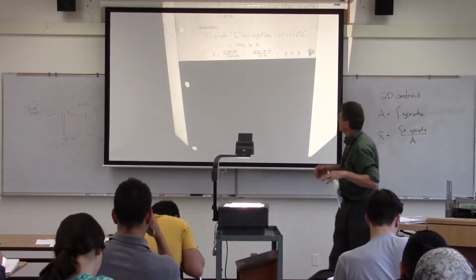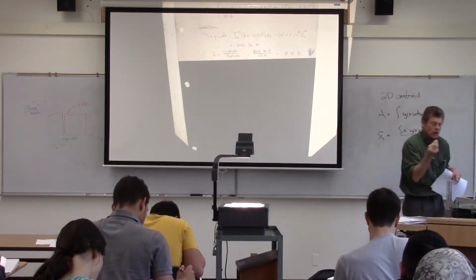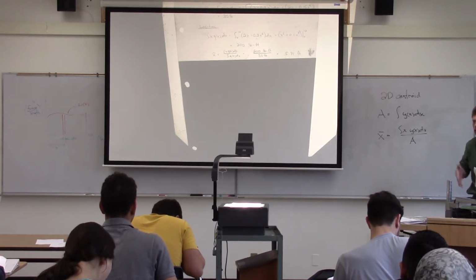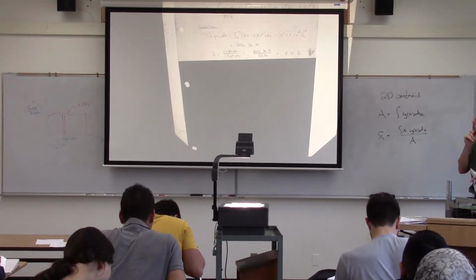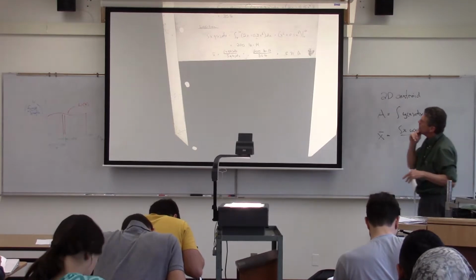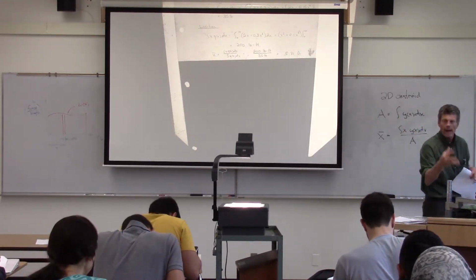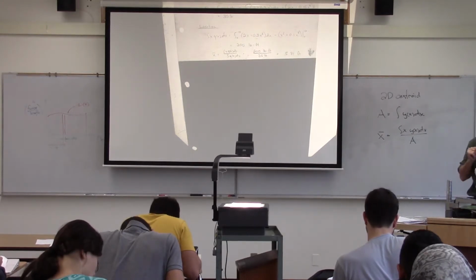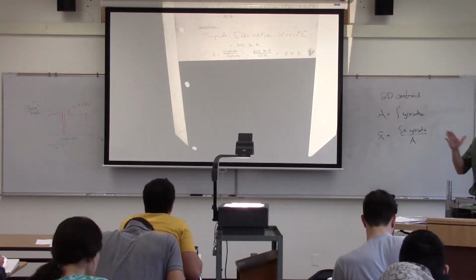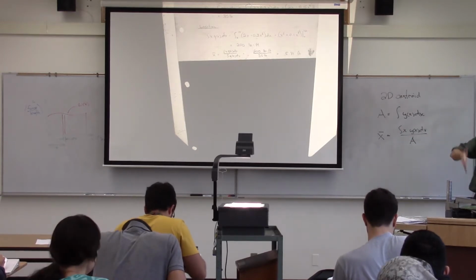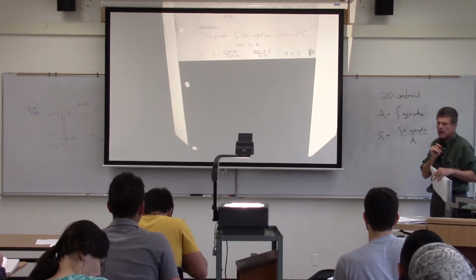And then finally, what I'm interested in is finding the location of this line of action. I simply take the first moment of area and divide it by the area. What I find is that from the origin, my A point where x equals 0, 5.71 feet over, is where this equivalent load of 35 pounds is acting.